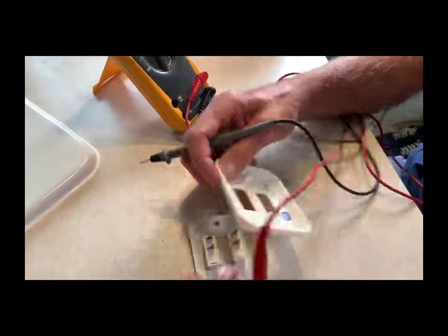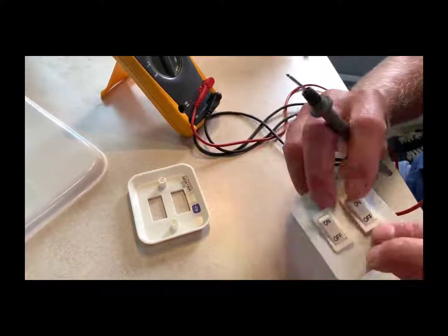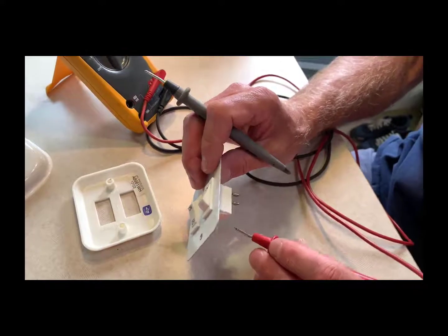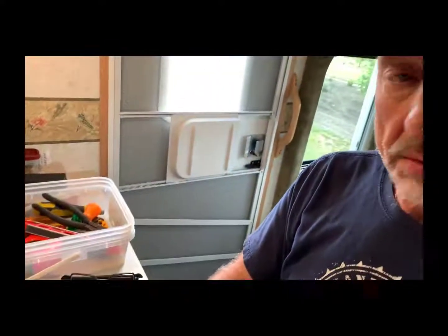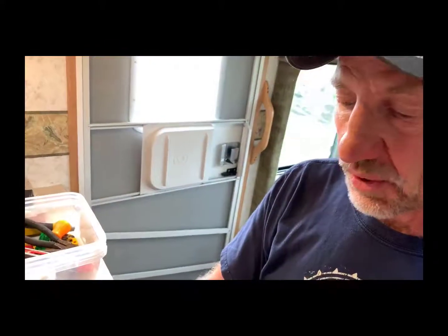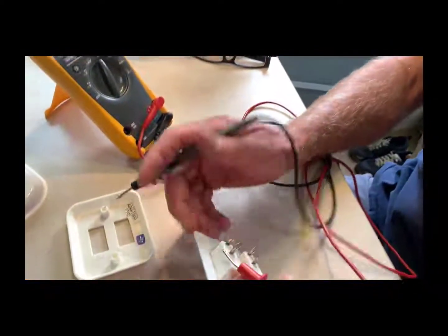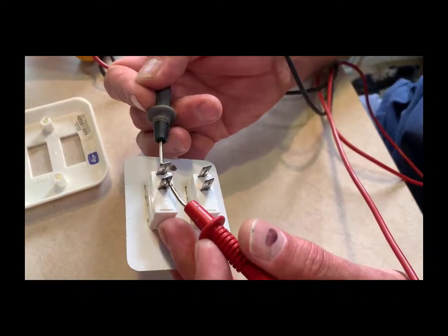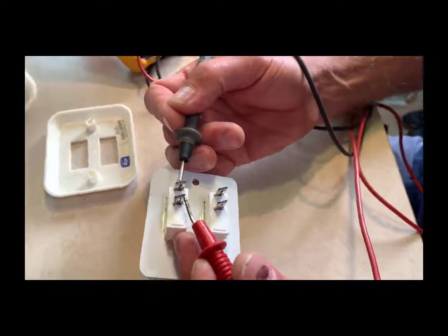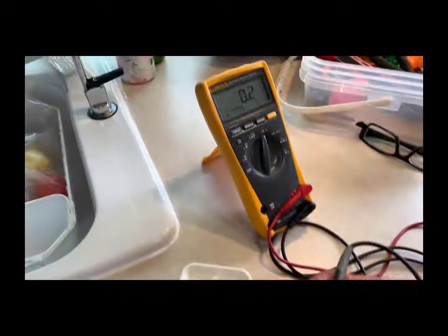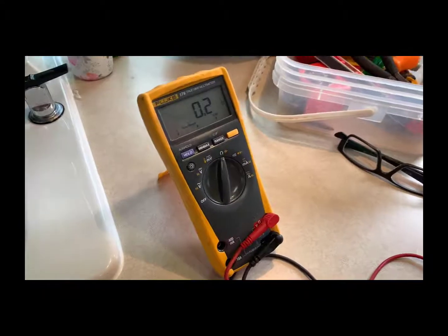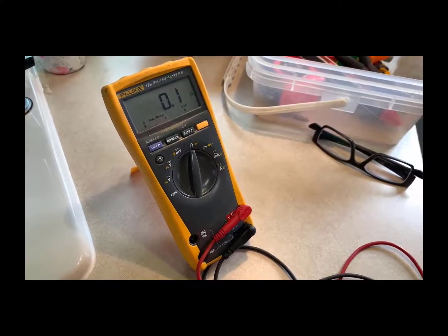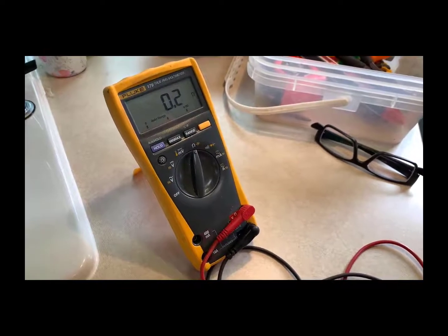Okay, now we're going to change the switch to on, and in changing the switch to on, we should now have a short circuit and 0 ohms of resistance, because this is going to allow current flow. So this is going to enable current flow in a circuit and allow the load to do work. So I'm just going to connect the leads here with the ohm meter, and you can see I've got 0.2 ohms, which is short circuit equivalent for a switch that's in its on state.